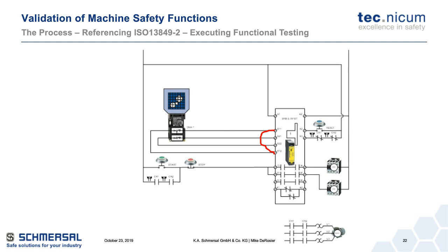I know some of you are probably sitting back going, wait a minute, actually introducing an electrical short circuit, isn't that a bad thing to do? Isn't that unsafe? We're talking safety here. The one thing I can tell you with these types of safety circuits, they're all low voltage. They're 24 volt DC. They're current limited. They don't create arc flashes like we're talking shorting out a 120 or 480 volt AC line. We're not talking about doing that kind of thing and not having proper circuit protection in there.